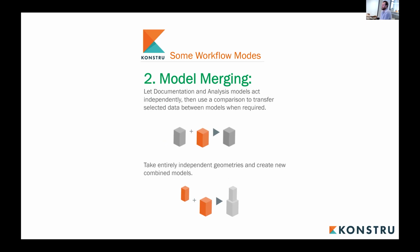But model merging is far more than that. You could move, let's say, a tower model onto a podium model and have them be merged together into one file. You could take one SAP model and add it to an ETABS model and extract from the SAP model all of the loading, etc., that's already present. So there are lots of different ways to do it.